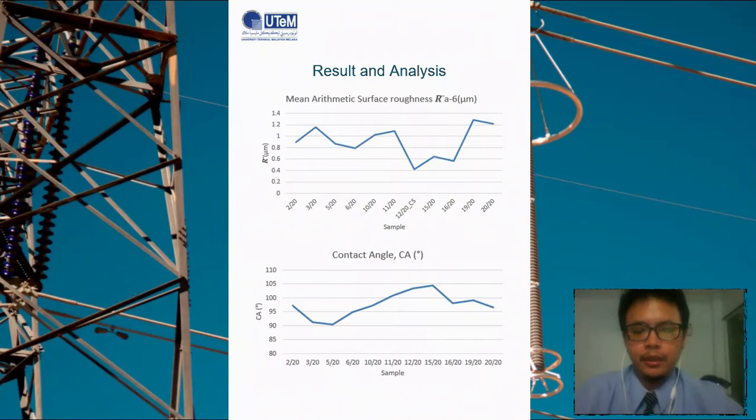Okay, for contact angle graph, it can be seen from all the shared test samples, including the control samples, that the contact angle from these three different locations is greater than 60 degrees, proving its hydrophobicity properties. The other chosen samples from a variety of shades and locations also show high values of contact angles, which are mostly greater than 100 degrees, confirming the insulator's hydrophobicity.